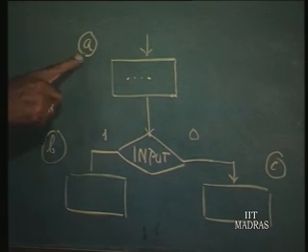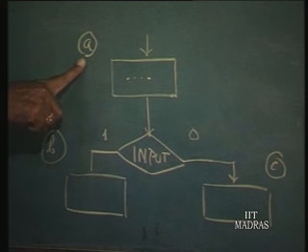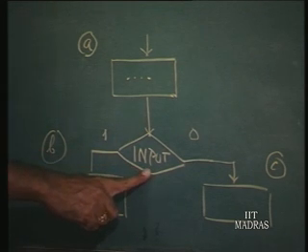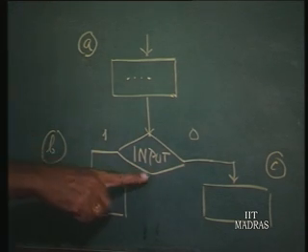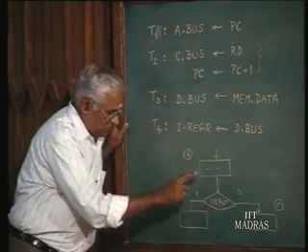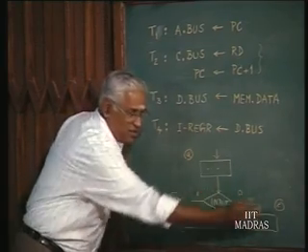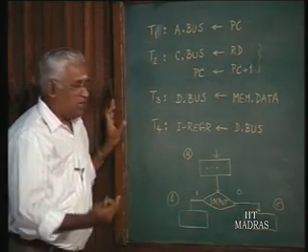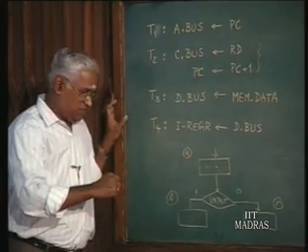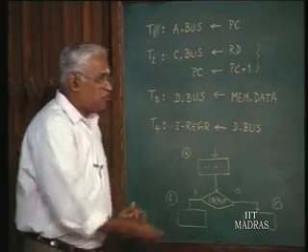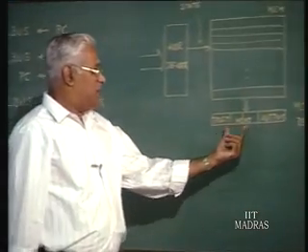Now, suppose this state happens to be T2. Try to recall, in T2 we were actually checking the input condition, or rather we may say we are testing the condition of the signal ready. Try to recall what we discussed earlier. In T2 we check ready, then depending on ready being 0 or 1, the next states are arrived at. In fact, I showed you 2 things. One next state may be T2, another next state may be T3, or one as TW, another as T3, whatever it is. So, now that particular information will have to be accommodated here.